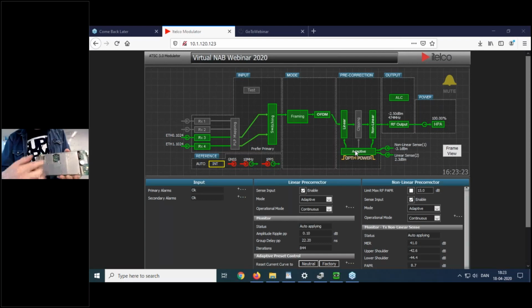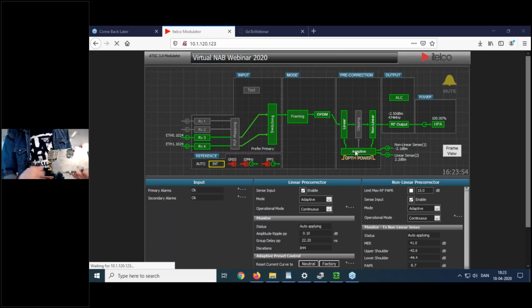So for that reason, when we mount nothing like this, we are compliant with the standards of the phase noise. Then we can mount an oscillator of a step higher quality, and the highest quality is one with an oven that will run 24 hours in an SFN without interrupting the service. And of course, the calibration of these oscillators goes together with the device so that it can be plugged in in the field without any skills other than putting in the screws, and then it will automatically calibrate.